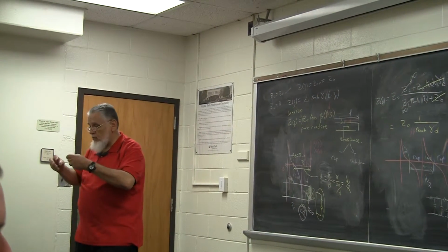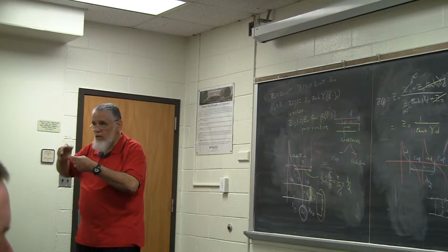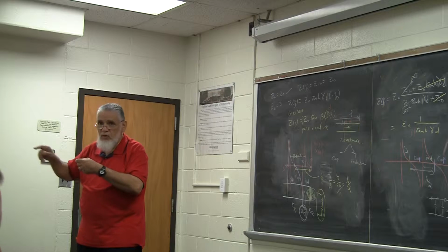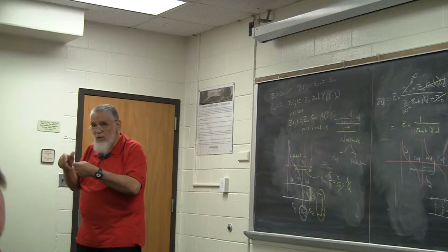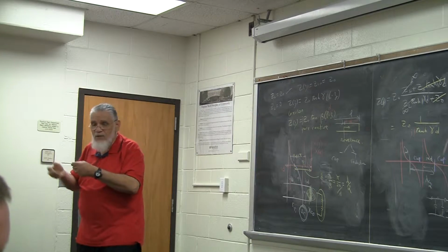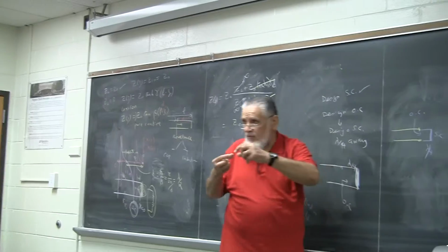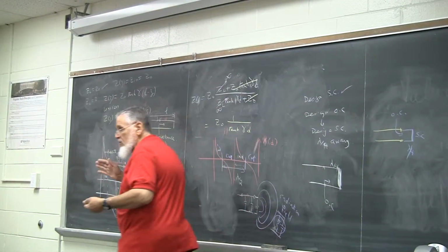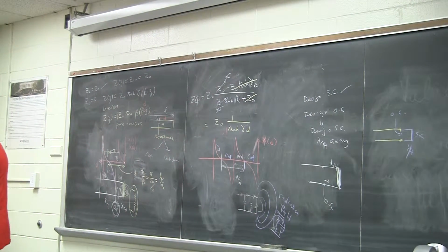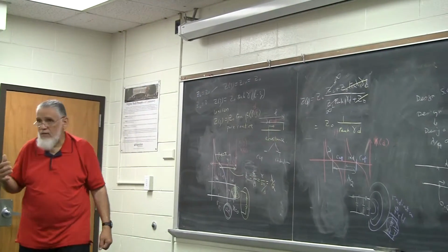So we go to the port and connect a short and make a measurement. We connect a 50 ohm load and make a measurement. We connect an open circuit load, you will be surprised, there is an open circuit load. And what is it? It's just like a short cavity that is designed to minimize the radiation, and that is calculated.